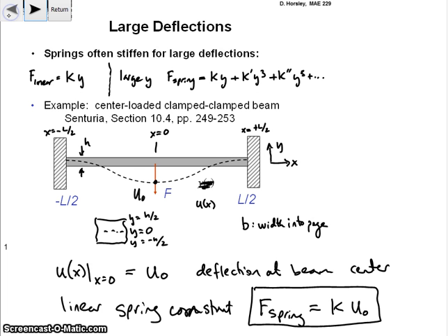Well, if I look at the shape of this beam, it kind of looks like a cosine function to me, right? It sort of has 0 slope at the boundaries, which is what it should have because it's clamped there. So the slope should be 0 here. And it's varying in this sort of cosinusoidal fashion. So it has a peak in the middle, and it has 0 amplitude at either side. And if you remember, right, the cosine,